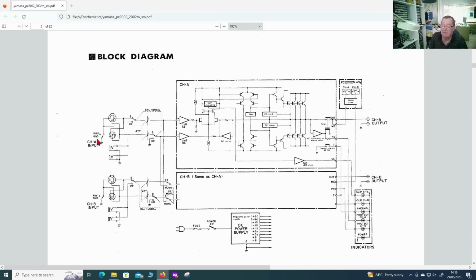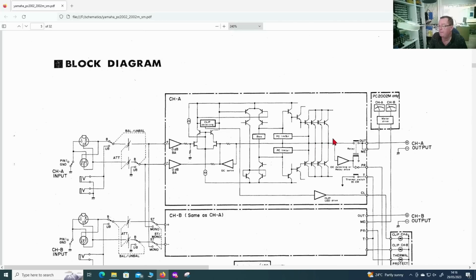And we can see we have the inputs coming through an operational amplifier type circuit and a differential amplifier. And that produces the signals going into the output stages. These are the output stages, and this is where the speaker connects. Here. This then is the junction between the NPN and PNP transistors that make up the output stage.